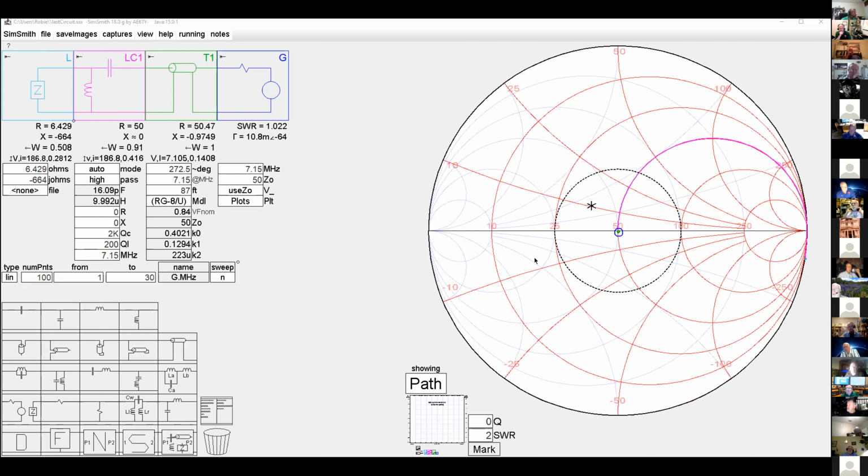Measure your antenna impedance, check your SWR, do some things like this. When you install a piece of coax, measure the length of it before you put it up as accurately as you can, and keep a record of what coax you have. It's just RG8 doesn't mean much. Belden 9913 RG8U means a lot more. You have to specify that.